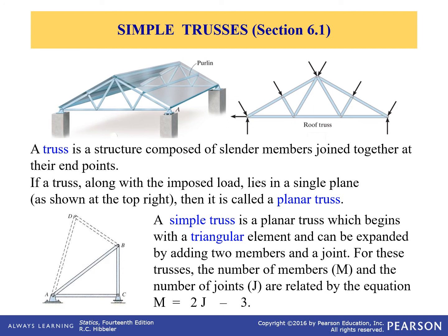So these trusses are made up of members. These members are going to be in either tension or compression, right? As a mechanical engineer designing it, you would need to figure out how to size these members so that they can carry the load that they need to carry. Trusses are loaded at the joints. So there's going to be two methods that we're going to see here in a moment to figure out how to calculate the forces at those joints so that we can figure out what's happening inside of this truss.